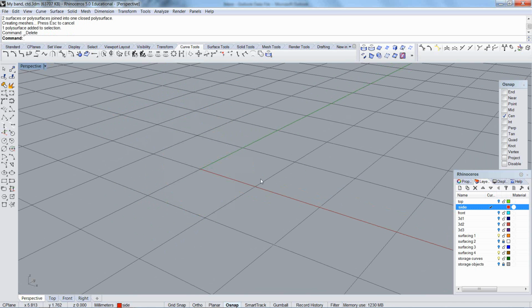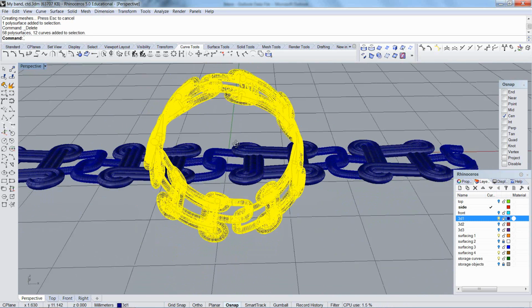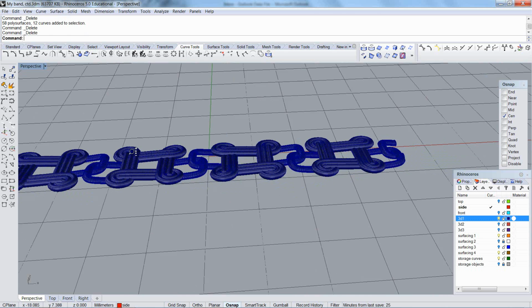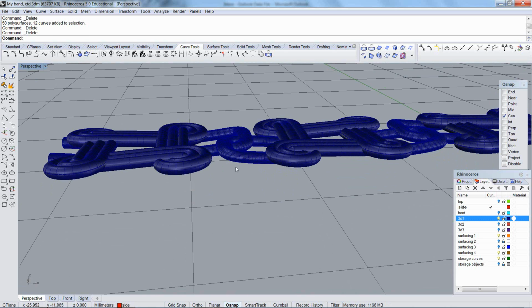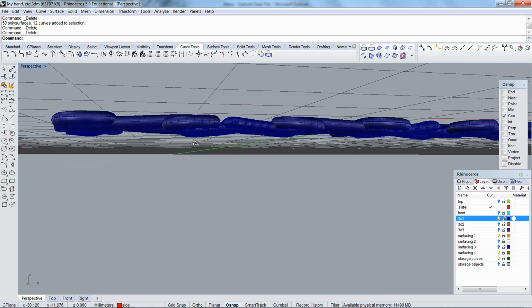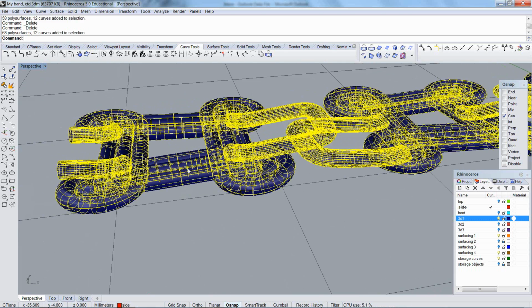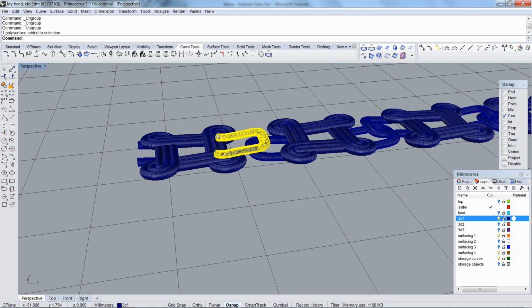Okay, so that brief introduction done, I'm going to Boolean my parts. You always want to Boolean flat. Okay, so you will begin with your flat parts. Now they're already in position for your flow. Everything should be good with them. All that needs to be done is that they need to be Booleaned. I'm going to ungroup, hit Control-Shift-G as many times as I have to until nothing is happening.